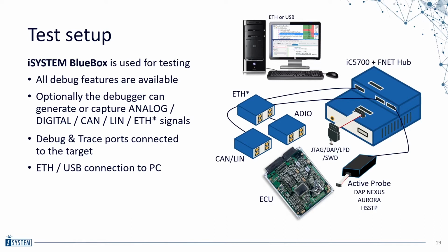And additionally, if the device supports a trace port, you can record program trace, data trace, and other trace messages. These features ultimately depend on the target MCU, so check with us if you aren't sure if your device supports trace. We'll check all the options you have. Sometimes you can use a larger pin device from the same family in place of the production device to get trace, just for development and test purposes.